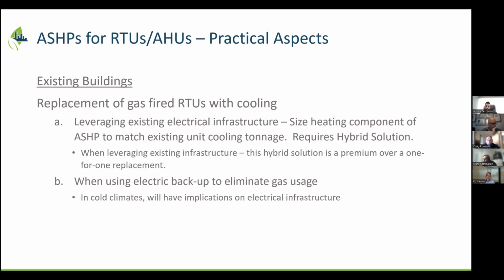Well, when a client wants to replace their rooftop unit with an air source heat pump and you are doing a like for like, the first thing you have to realize is that the rooftop unit has been sized for the cooling load, not the heating load, at least on the refrigeration side.